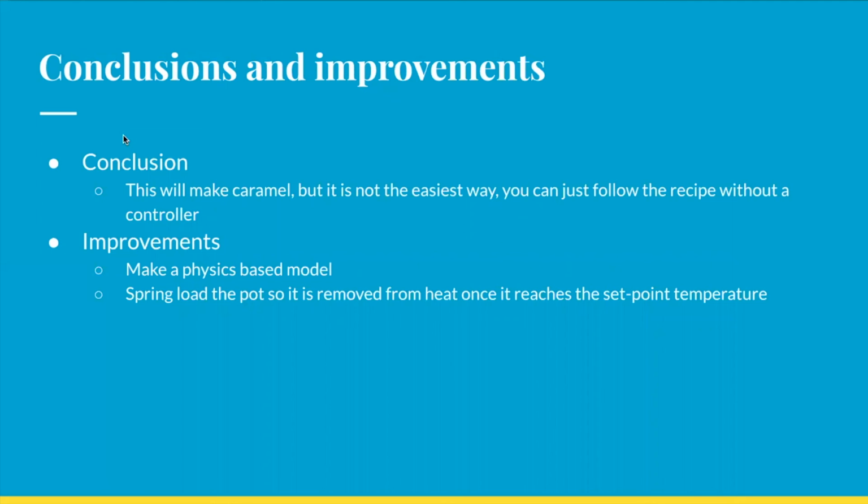But the key takeaway that we wanted to remember, and would suggest for more improvements on this study, would be to include a physics-based model that would take into account this heat transfer and mass transfer together. I think an ideal controller would have parameters for when it's increasing the temperature until we get to the phase change boundary, and having different tuning parameters to get through this phase change boundary until we can then reach our set point.